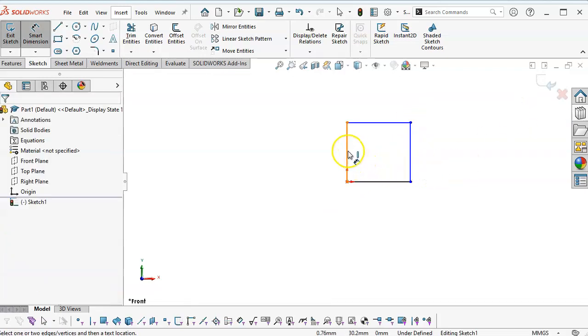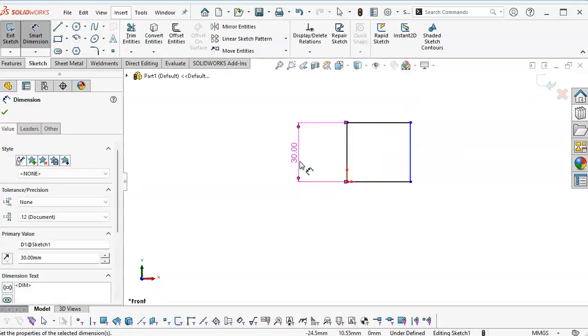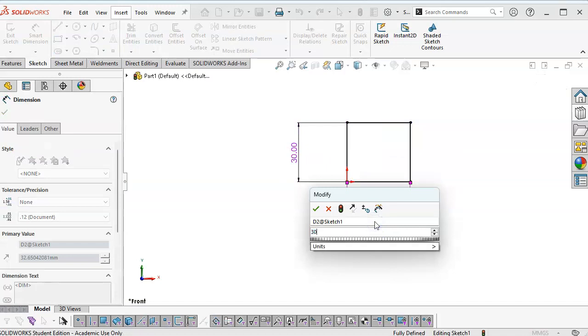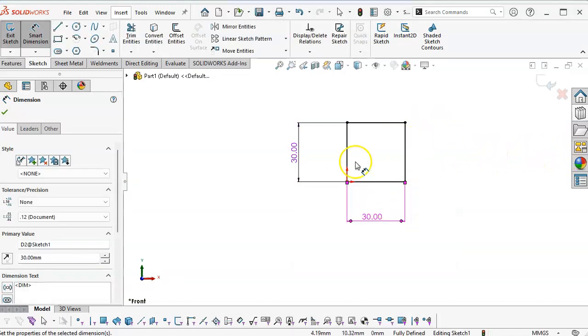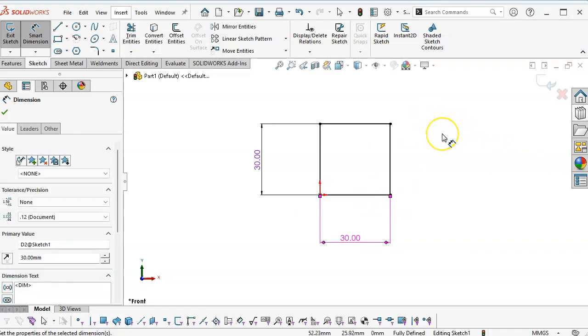I also know that even though this is going to start off at 30 by 30, I'm going to be adding geometry to it. So I don't necessarily want to make this square. The other thing I would have to do is decide, do I want to include the hole in the sketch and try to drive this with a linear pattern, or do I want a feature pattern so that eventually I can just take advantage of my save as and open, and then eventually build this into a configurable item for the plates or the spacers? We'll come up with a common naming convention to work from.